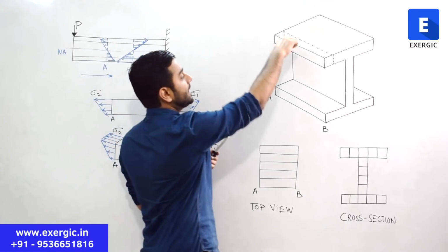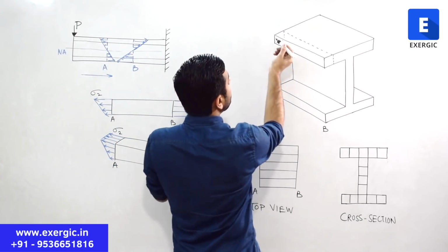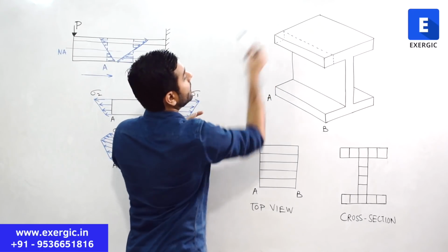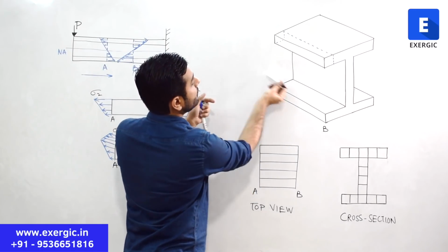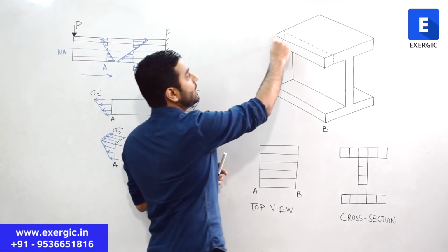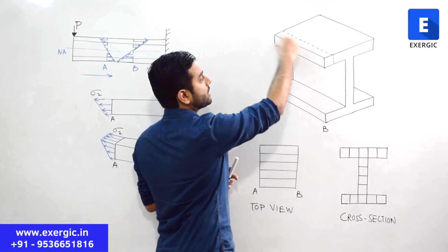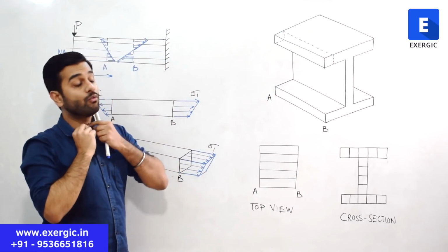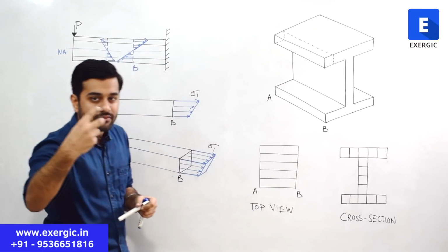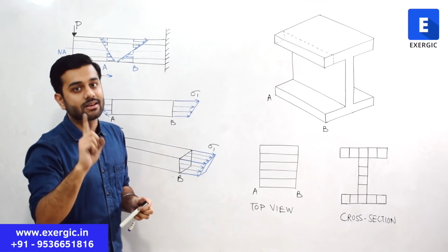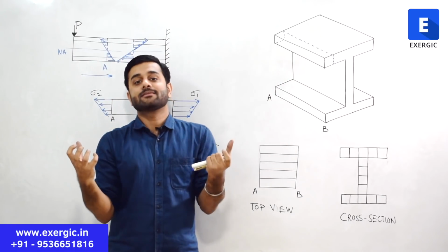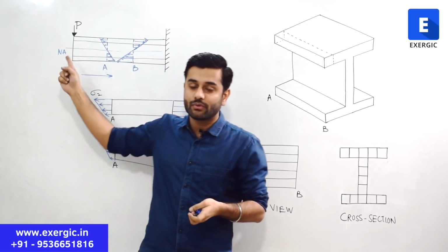Similarly, on the back side of section A, there will be tensile stresses moving out from the normal area, and in the lower half, compressive stresses moving into the normal area, right? If you look at only this part here, tell me what type of stress is going to act. What type of stress will act in this fiber that I have considered? Tensile stress. In this case, this part is going to get tensed because it is above the neutral axis for such a loading.